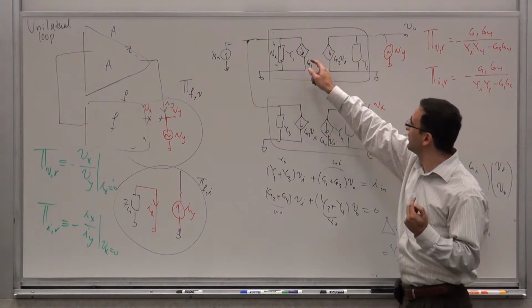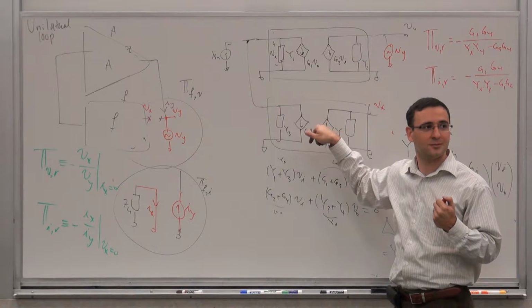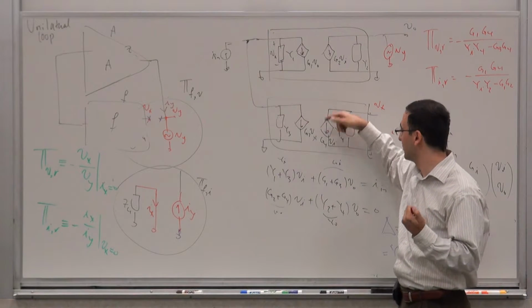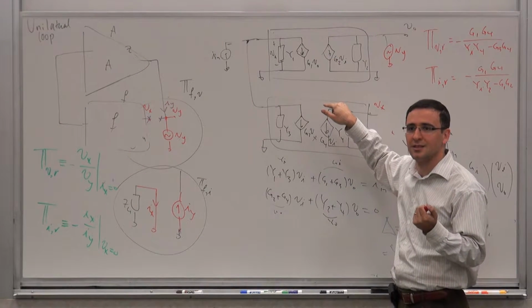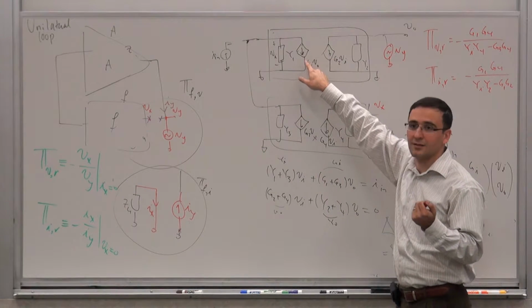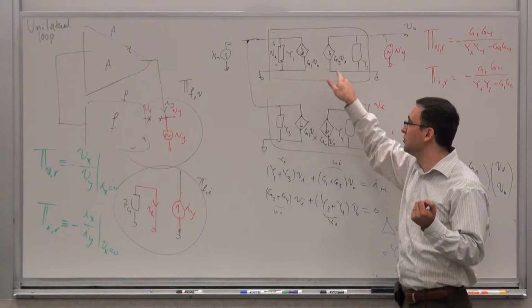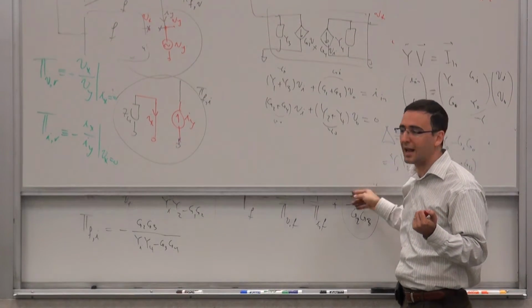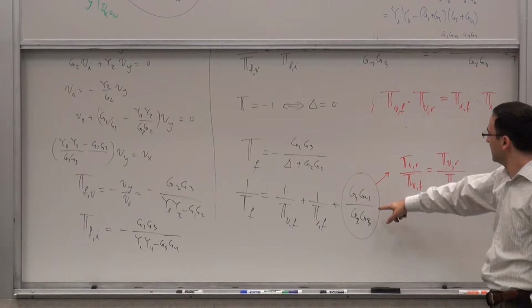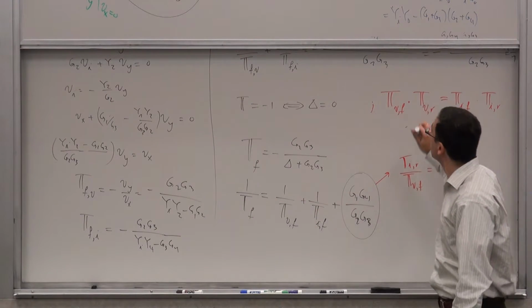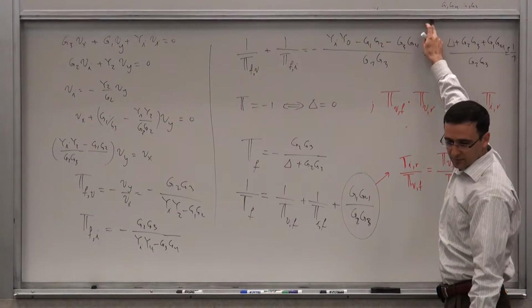So one of the reverse gains is 0. If one of them is 0, what happens is that the signal cannot travel in the opposite direction. You either kill it here or there. And as a result, your loop is unilateral, which means that for a unilateral loop, you have the correct result. And then for bilateral, it's basically this expression that we derived earlier.